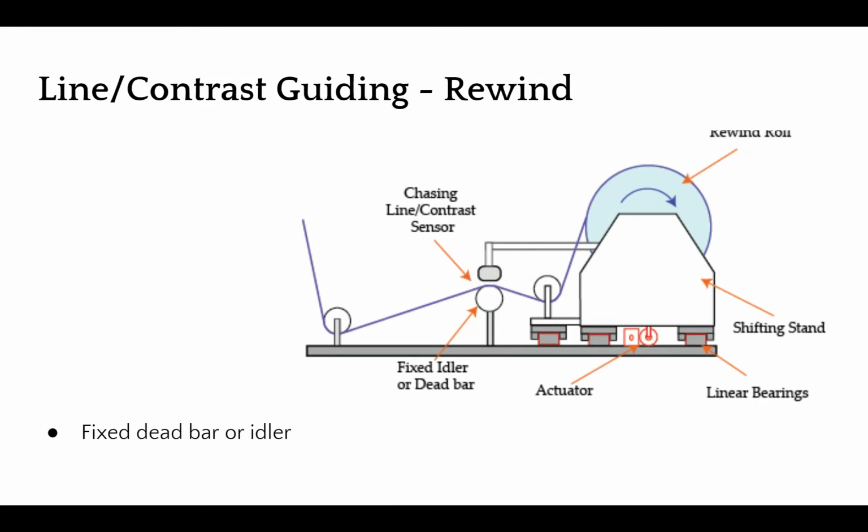Let me see if Carlo has any other comments about that. But to me, exponential moving average is the simplest one and easiest one for us to implement. This is just purely for filtering the edge position. Obviously, you can have some advanced control system where it has a filter built into the controller itself, like an adaptive control or things like that.